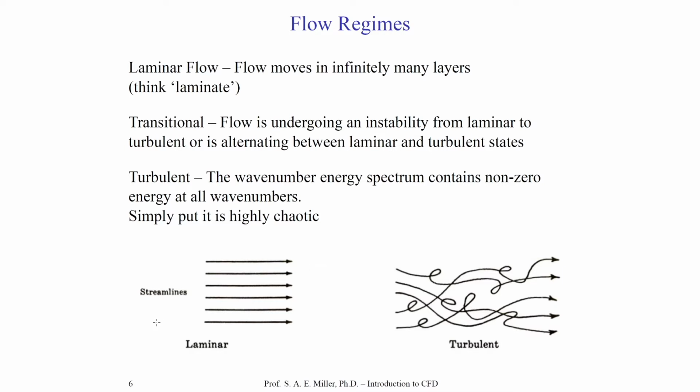Now in the lower left corner, we have plotted some streamlines of perhaps a laminar flow. In this case, it's this nice simple flow moving from left to right. In the turbulent case, on the lower right of the screen, you'll see some streamlines going around in curls in every which direction. It's almost unpredictable in a deterministic way. In fact, in CFD in general, we are going to be predicting turbulent flows through statistical approaches and not through simply finding the solutions to the equations by integrating them, which is one particular approach to CFD.